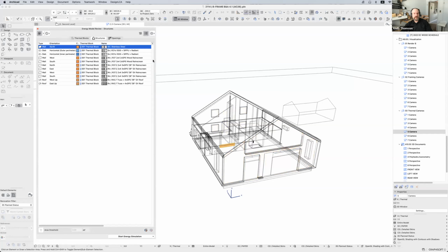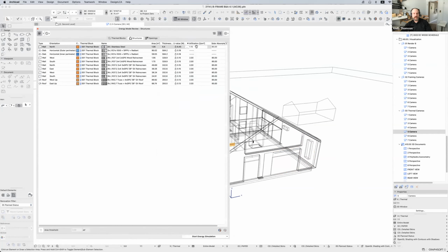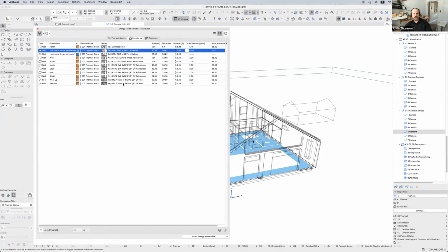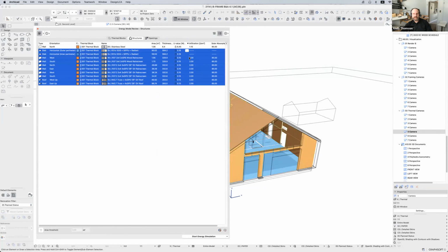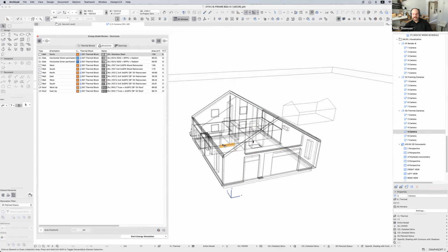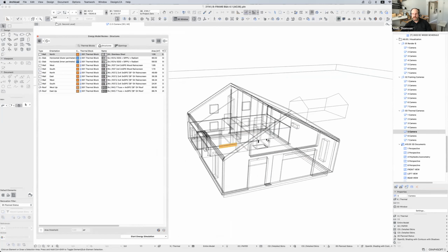When I'm sorting through this, if I stretch this a little wider, I can see that I've got these U values. For every given piece of structure, I've got an infiltration level of 2 and a U value that's 0.15, 0.13, and then I've got this one thing that kind of offends me. I don't know what it is, but it's high. It's like 6. It turns out it's a backsplash from the counter.